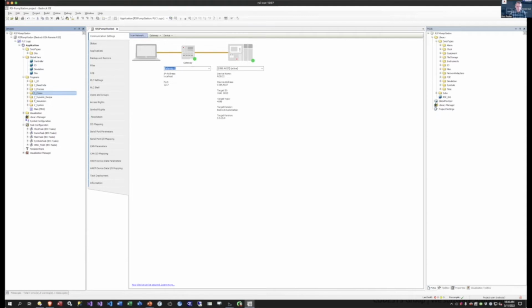If I have external communications to other PLCs, I'll put that in the COM section. I also have some recipe code that I have in every controller. And that's all standard in mine. And then if I'm doing any simulation, I have a simulation section. And lastly, any system events that I might run. So I might have an on start event, or anytime there's an online change, I might have to initialize some stuff, things like that. So that's kind of how I break up my programs.